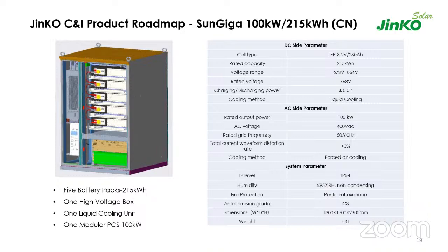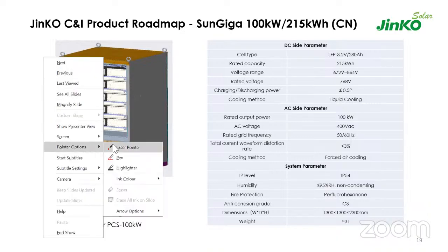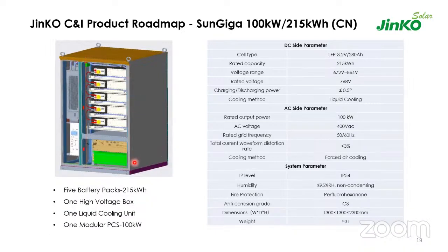So you can see this particular image, let me just try to show you. Yeah, so this is the cabinet. Within this cabinet, you can easily see that this segment, here we have 5 packs. These 2 segments make an all-in-one solution. If this is not an all-in-one solution, it will have only the battery bank, which means here we will have 3 more racks, where instead of 215 kilowatt hours, the capacity becomes 344 kilowatt hours. Yes, India has got only AC loads.